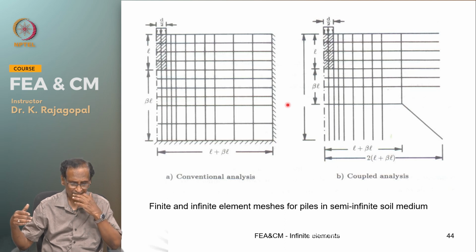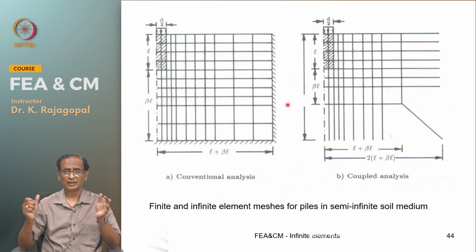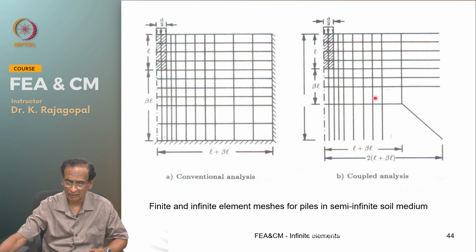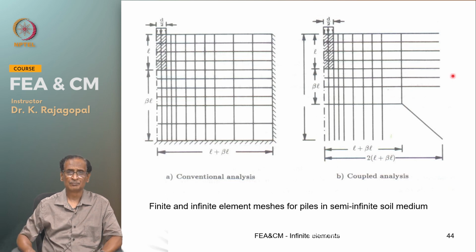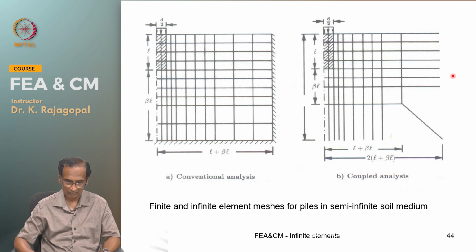So finite element analysis of piles usually involves very huge meshes. If we can save on the size of the problem by intelligently using infinite elements, then we can have much faster solutions.